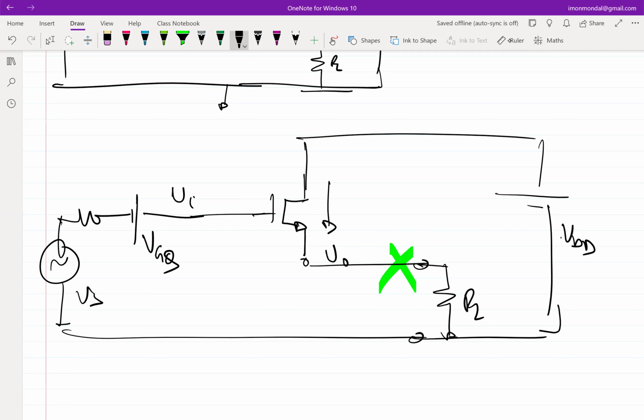So let's assume that RL is something which you cannot connect directly. I can capacitively couple, assuming C to be infinity. So then how do I bias this transistor? Okay, let me repeat. What I am saying is that often RL is not a physical resistor that is available to you. It is quite common that it's a modeled resistor, the input impedance of a next stage or something.